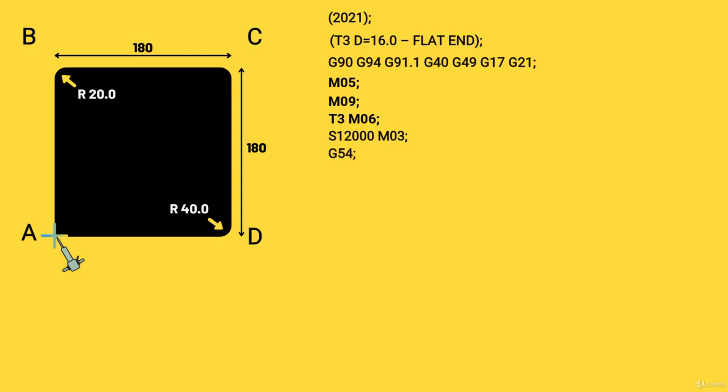In the next line, G54 sets our working datum. G54 just tells the machine to read the information of our chosen datum so that all our dimensions and measurements come from the datum position on the bottom left hand corner of the part.